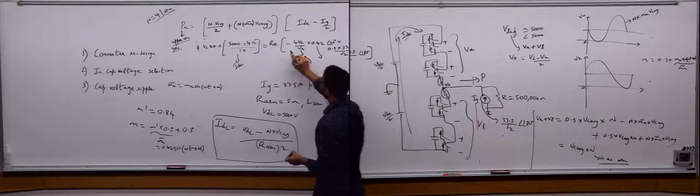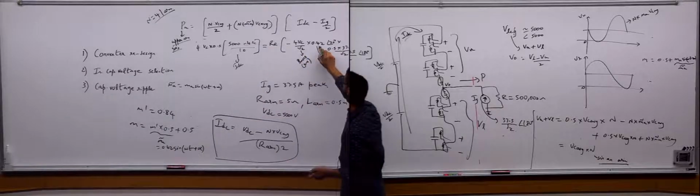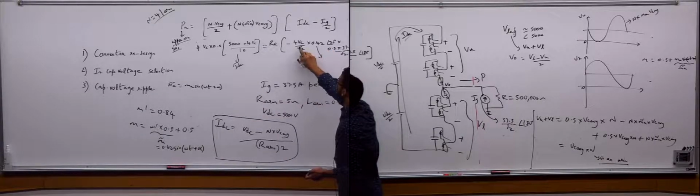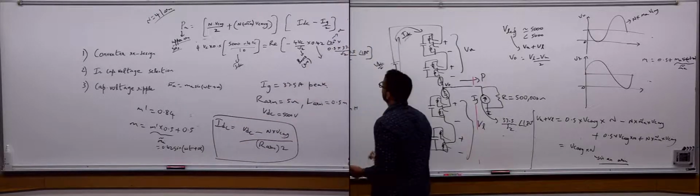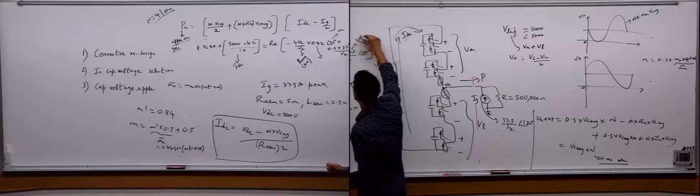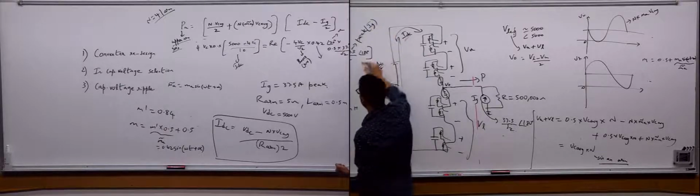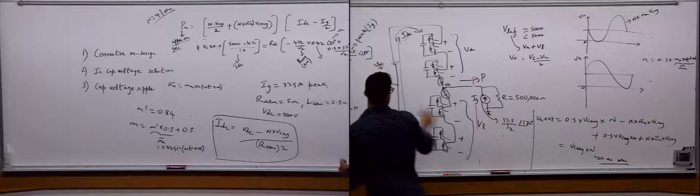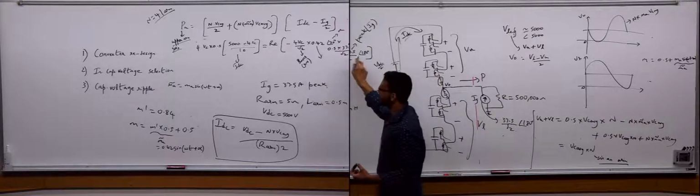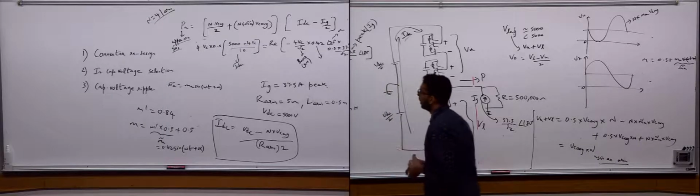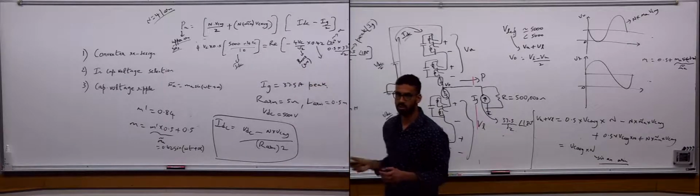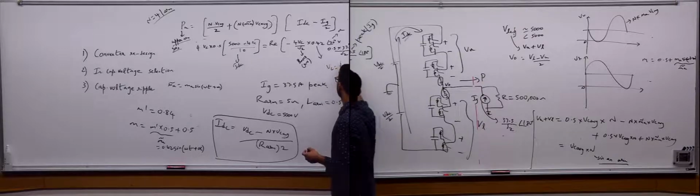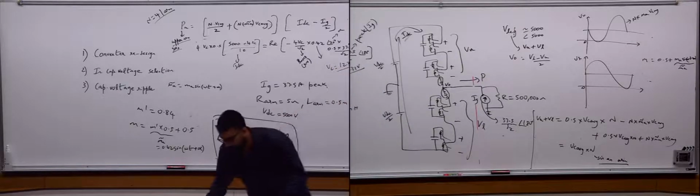So this in phasor quantity is 0.42 times n Vc average, 0.42 by root 2, that is a phasor. Angle of alpha is 20 degrees, times this is peak of Ig, so in phasor quantity that will be by root 2 and it has a phase angle of 180 degrees in simulation. So that is that. Then if you solve for Vc from this, you get Vc to be 1231 volts, and you see that in simulation.